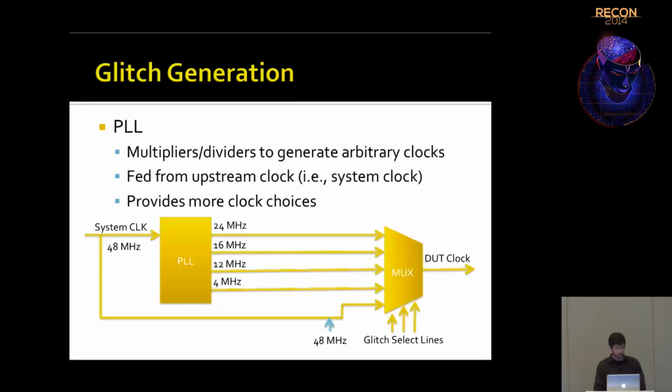So the next idea was to use a PLL if you have one, either a discrete PLL chip, or if you're using an FPGA, most of them are well equipped, where you just literally configure the PLL's outputs to whatever frequencies you want.